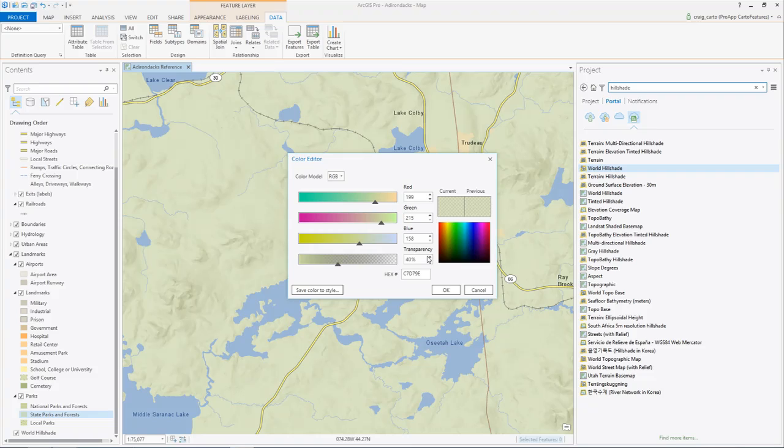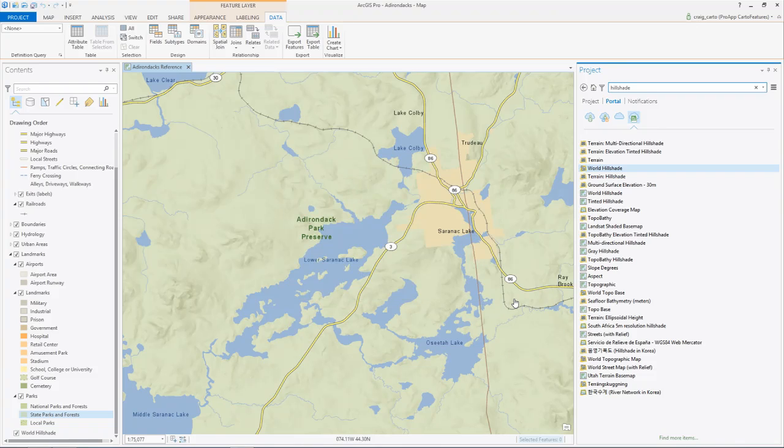You may be used to ArcMap where you could do only layer-based transparency or attribute-driven transparency. We still have those capabilities, but you can do color-based transparency in ArcGIS Pro. And color-based transparency operates differently than layer transparency in that you'll get additive blending of colors. So if you have 2 features overlapping, they'll blend together, whereas with layer transparency, it's done as an isolated blend of the entire layer stack. So it adds some capabilities to have some nice cartographic effects.